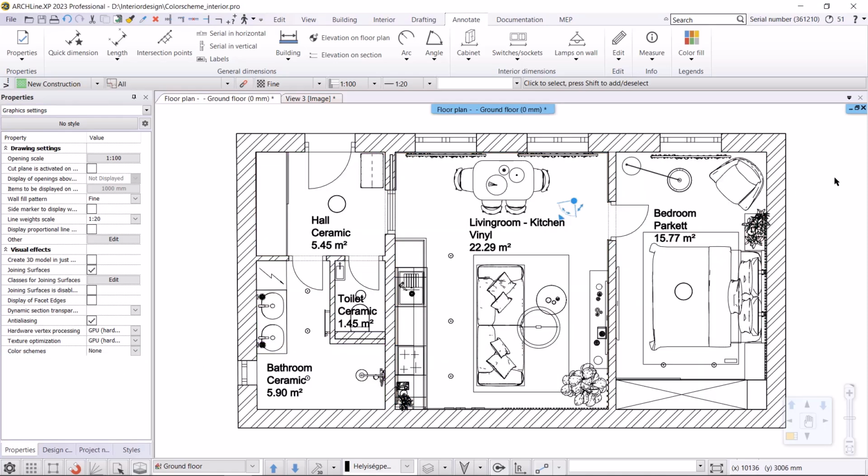The last topic that I show you, which I think can be very useful in our work, is when we download objects from the 3D warehouse. It's important to be careful not to download models with too high a polygon count. If we don't pay attention to this, we now have the possibility to use the color schemes to color the objects according to their complexity. This way we can see which objects have too much surface area and could slow down our project.